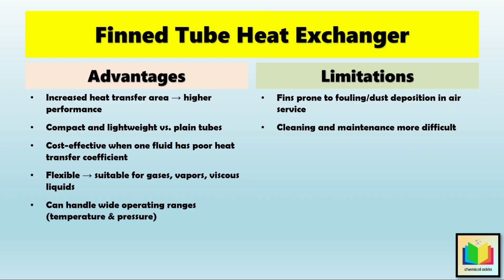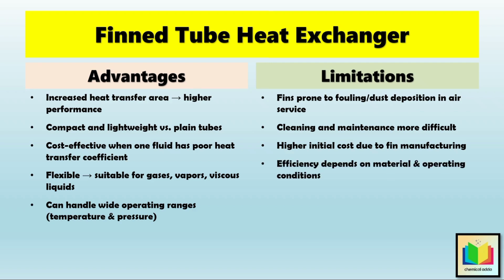Then next limitation is, the manufacturing and attachment of fins add to the initial cost, and their efficiency depends heavily on the choice of material and operating condition, and if the design is not correct, the expected benefits are lost. In addition to this, one more limitation is, mechanical damage, such as bending or corrosion of fins, can significantly reduce performance in a short period.